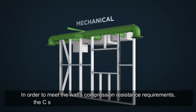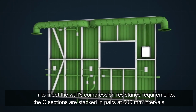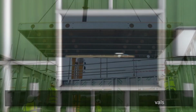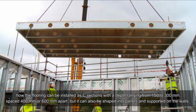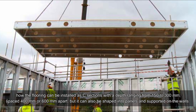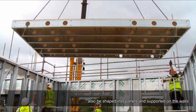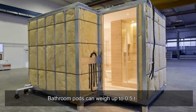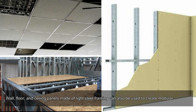In order to meet the wall's compression resistance requirements, the C-sections are stacked in pairs at 600 mm intervals. The flooring can be installed as C-sections with a depth ranging from 150 to 300 mm, spaced 400 mm or 600 mm apart, but it can also be shaped into panels and supported on the walls. Bathroom pods can weigh up to 0.5 tons. Wall, floor and ceiling panels made of light steel framing can also be used to create modular structures.